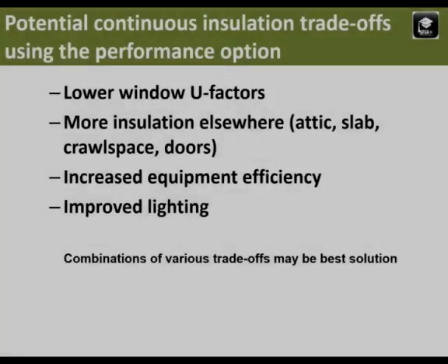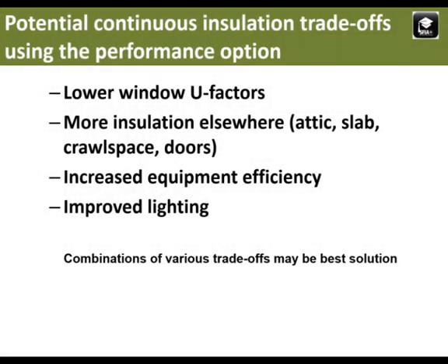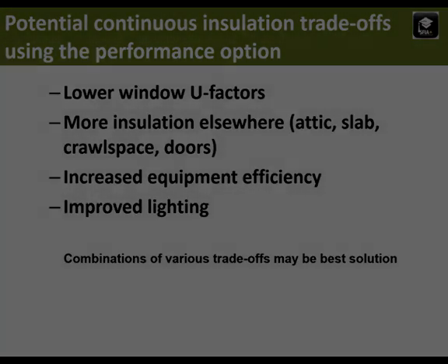The most common trade-offs required to offset some or all continuous insulation are shown here. For example, better windows would be a good trade-off in the southern climates. Similarly, shading of the building can be used to trade off insulation in the walls, ceilings, or other components. Other options include window area decreases, internal shading of glazing, mechanical ventilation energy, reduced duct leakage, or better lighting designs. Some credit can also be given for on-site energy generation.